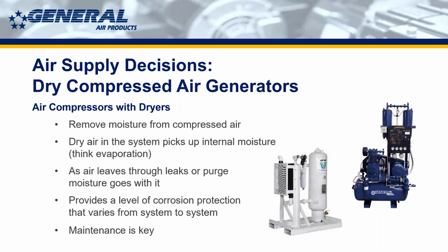And lastly, and I make this point with every piece of equipment, every technology, maintenance is key. If you do not maintain the dry air pack, you will not get the dew point that you need. If you do not get the dew point that you need, you will not be mitigating corrosion.